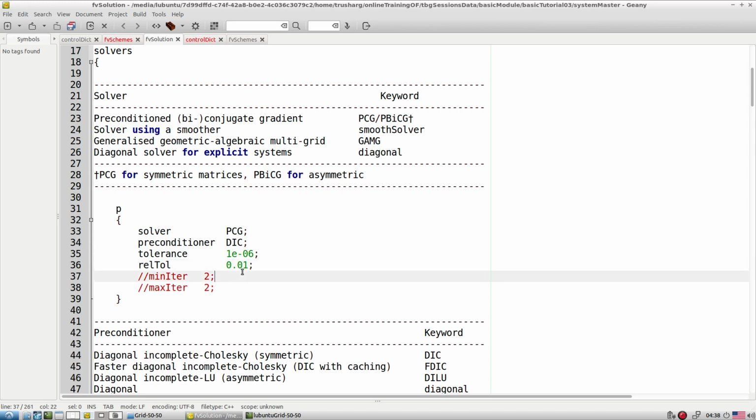If you see the entire calculation, we have a chance to stop the simulation in three ways. One is when the residual falls below this solver tolerance. If the residual falls below this solver tolerance, then the linear solver stops, or maybe the ratio of current to initial residuals falls below the solver relative tolerance. What does it mean? The ratio of current to the initial residuals.